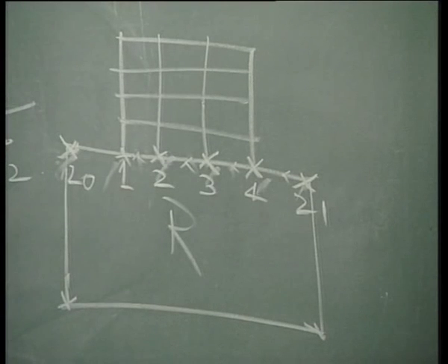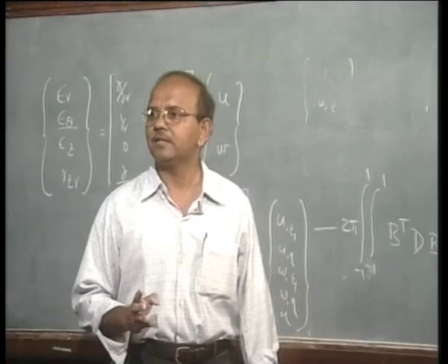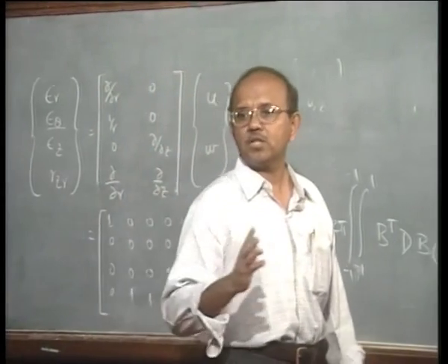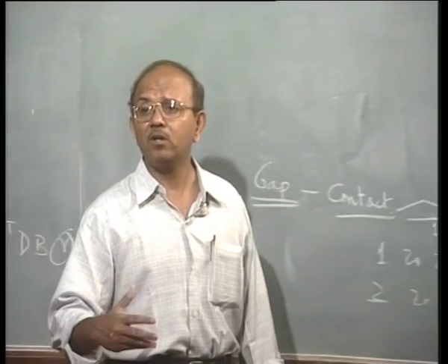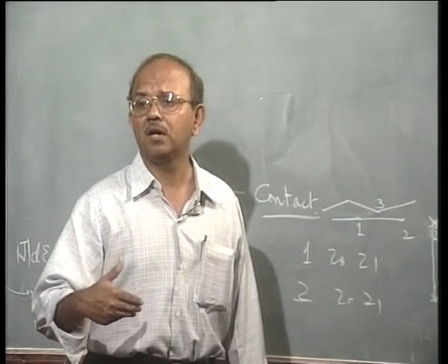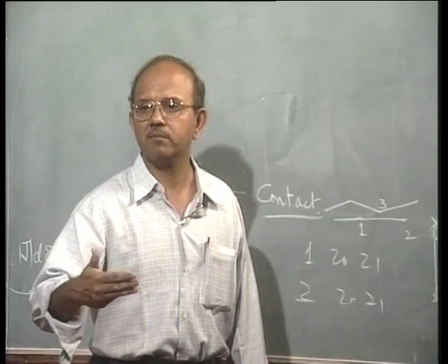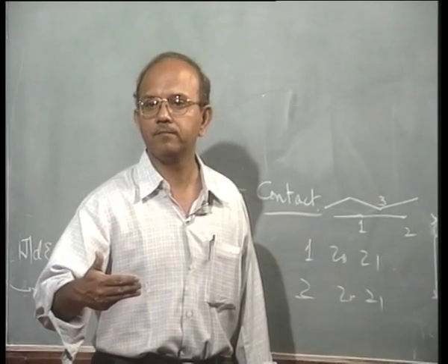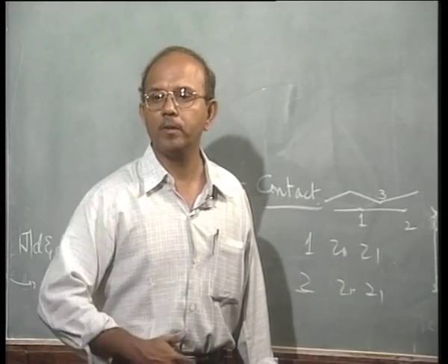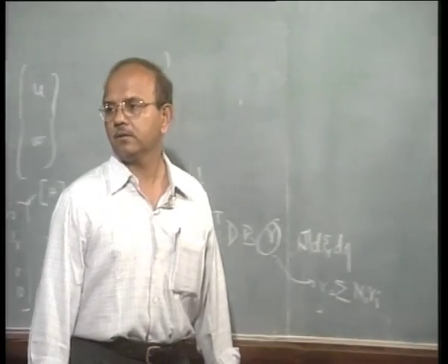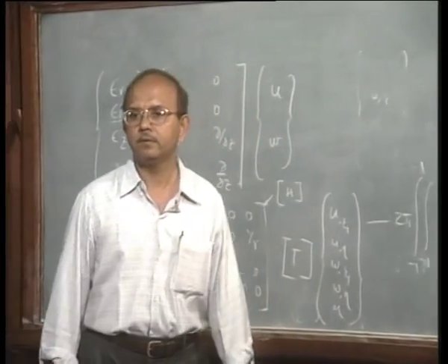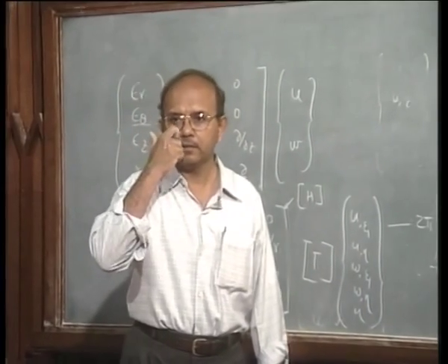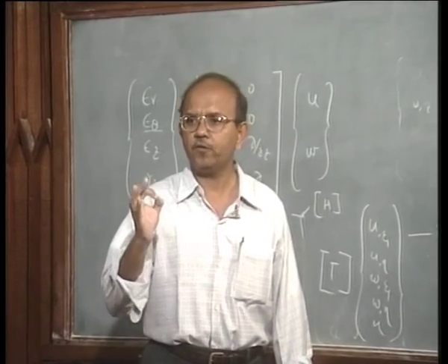The problem in contact algorithm is that the algorithm's stiffness matrix is written in such a fashion that the slave nodes are not allowed to penetrate, but unfortunately the master nodes have no such restrictions. Master nodes are allowed to penetrate. Okay. Is that clear?